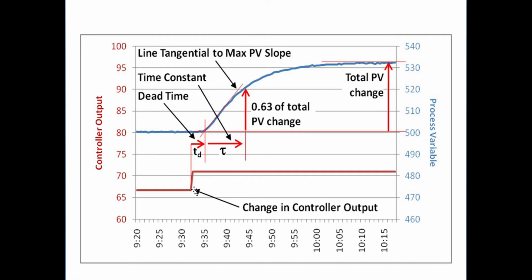After the controller signal we have issued, the time taken by the process to respond, you can see this is the controller output, right? The controller output begins here, but the process starts responding from here. So this portion td is nothing but the dead time, right? So these are the basic ideas of dead time and time constant.